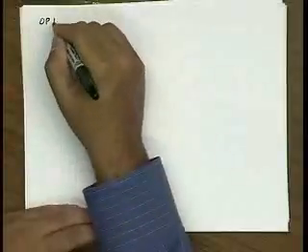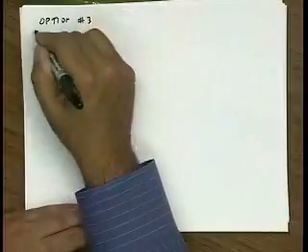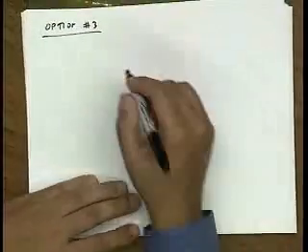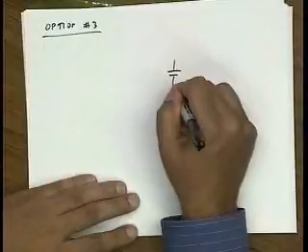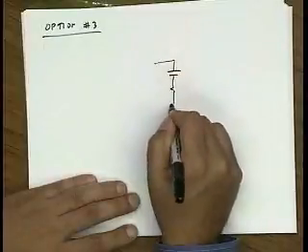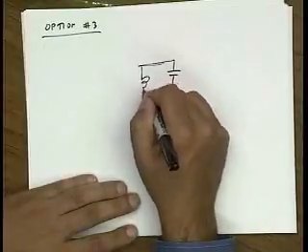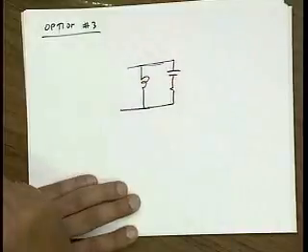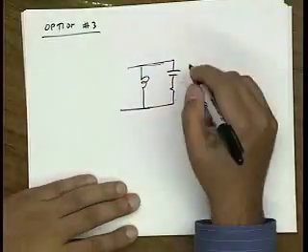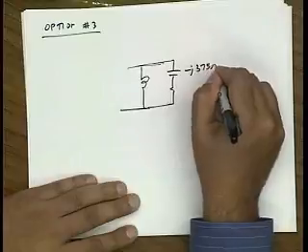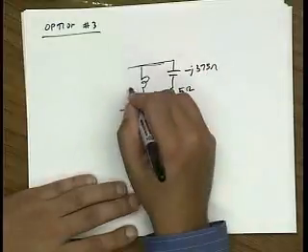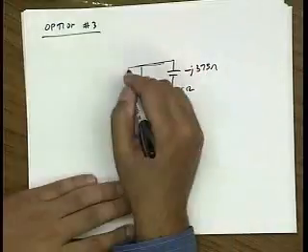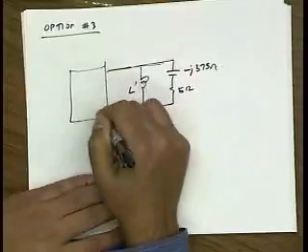Okay, well, let's not give up yet. Let's try something else. Instead of using a series resonant circuit, let's do a shunt resonant circuit. So I put an inductor in shunt with my transistor, and this is L prime, and then I use my matching network again.